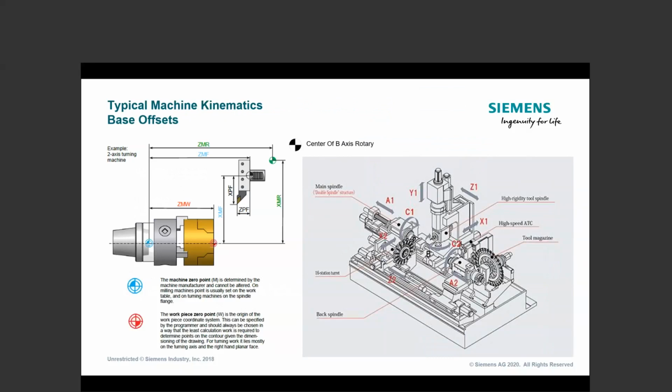So the preferred method, and certainly our encouraged method when commissioning a machine, would be that your main spindle is your primary datum. So all offsets, all movement will basically move relative to that main spindle. So in this case, all travel based off the machine 0 would be a plus direction, including my sub-spindle. So if you look at any offsets, let's say I put the front of the part where that little red bullseye is as my part 0. Maybe that's my G54 or 55, 56. I would expect to see now a positive value get inserted in the offset.